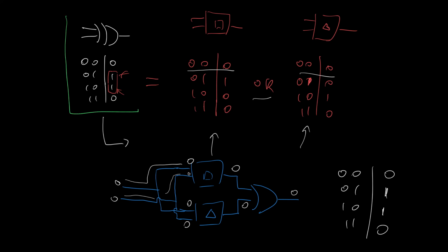If I have an AND gate, its truth table is going to be 0, 0, 0, 1. And notice that an AND gate has only a single 1 at the output. That there's only one time when the output is a 1. And that's true of this gate, and that's true of this gate. So we just somehow have to rearrange the rows of an AND gate, and we're done.